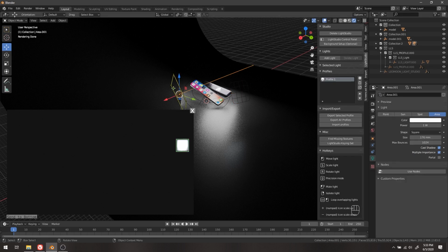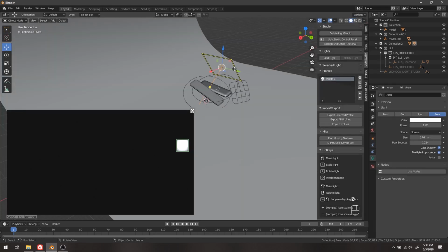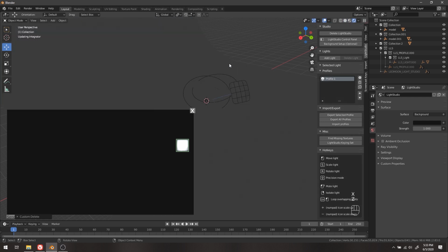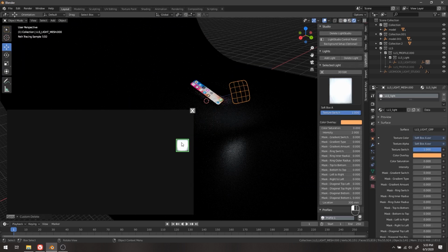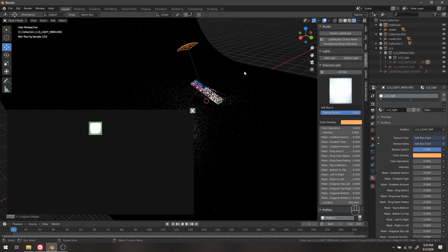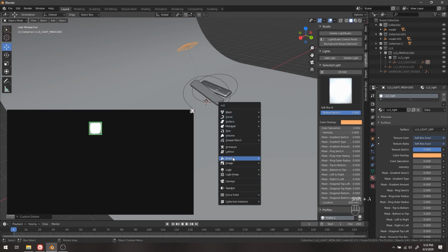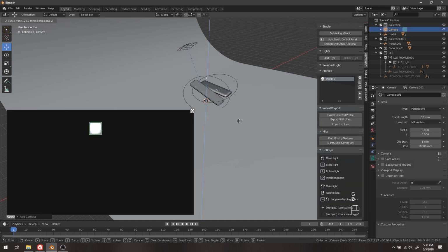We're going to go delete those lights we made previously. I'm going to switch on over to the other view so I can see it, and then back to render preview. And then you can start designing the lights. Now, the other important thing we need to actually render something here is a camera. So, like I mentioned earlier, Blender does not render from the viewport, it renders from the camera view. So you're gonna hit Shift A, camera, grab it up in Z so we just know where it is.